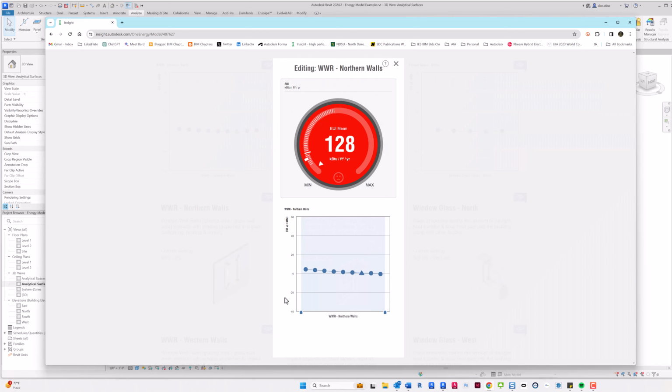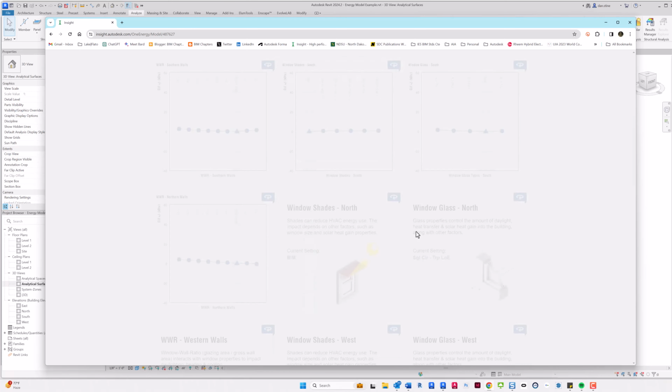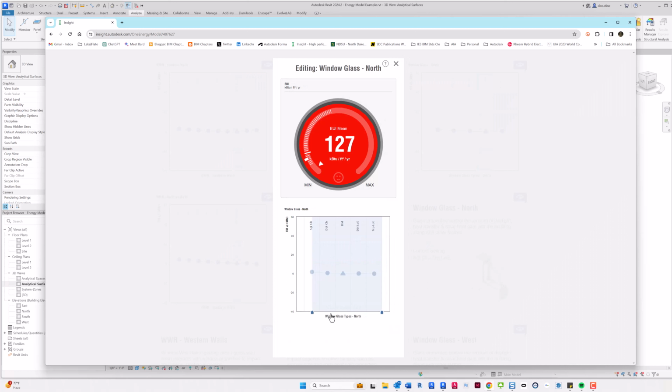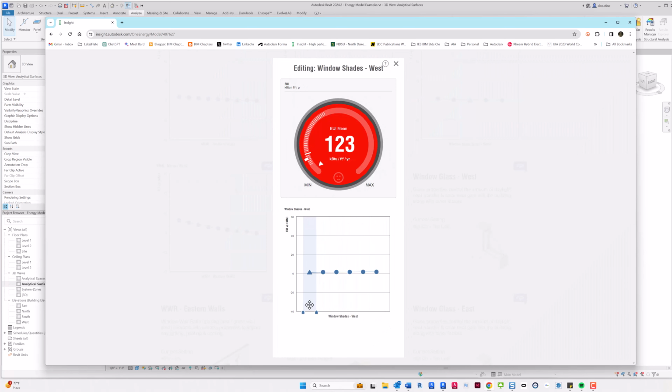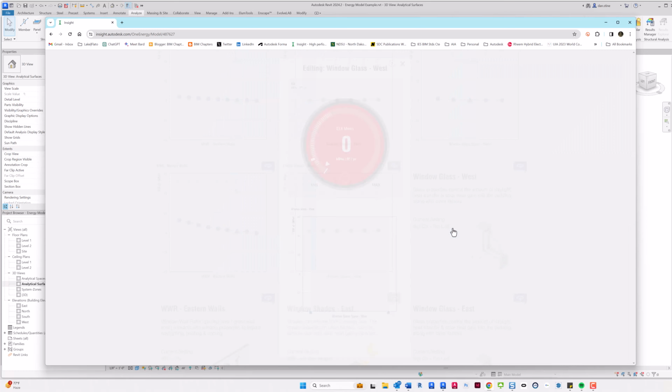The slope of the graph actually indicates how much potential there is to save energy for that particular input. The glass setting again. The west side, obviously, this graph is steeper because of the long west side of the wall. If you have more window area, it's going to use more energy. That's what that graph was showing.